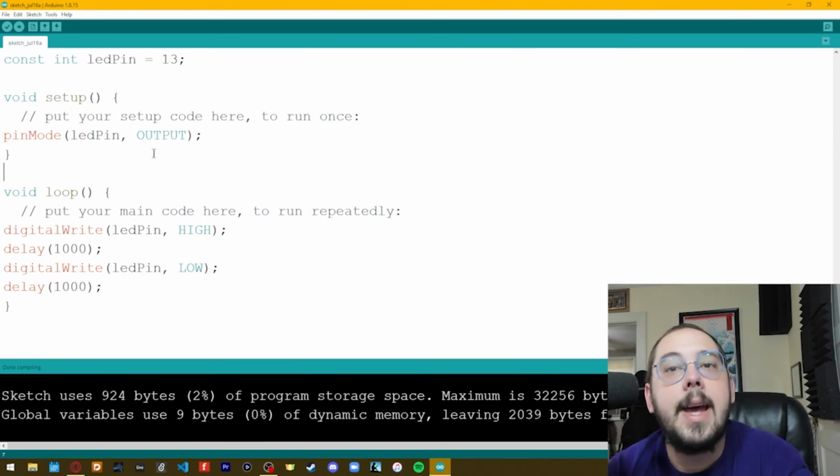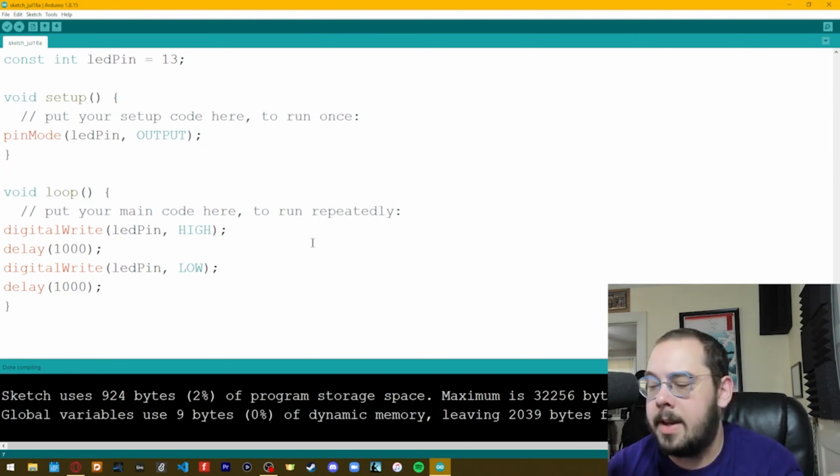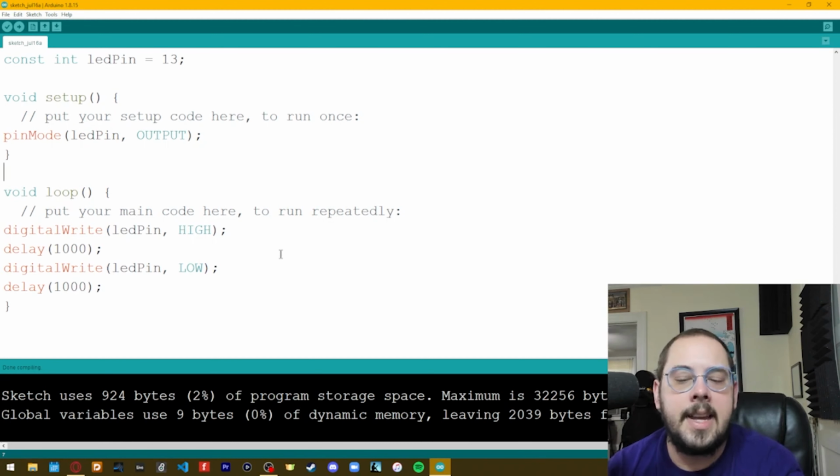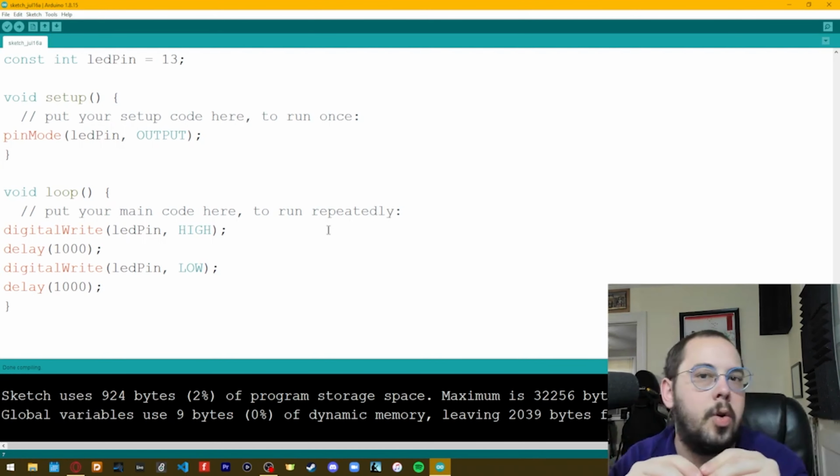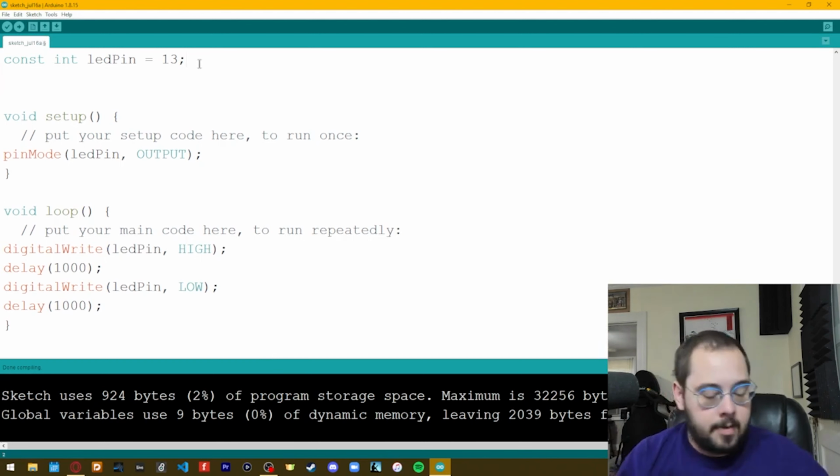What I want to do next is now add in a digital input. So the digital input, as we'll see, is any digital signal that is being received by the Arduino. So it is sending that data, or that electricity in, and the Arduino is responding to, is there electricity, yes or no, on a certain pin. So to do that, I think a button or a switch is pretty straightforward. So let's work with a button first.